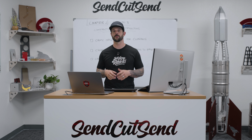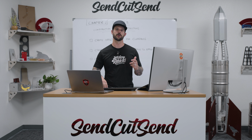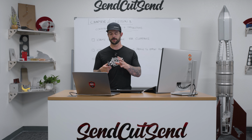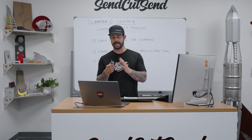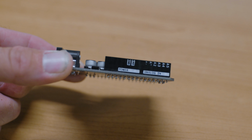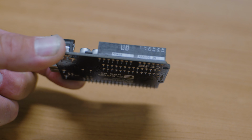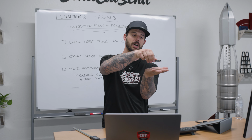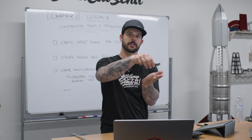In the last lesson, we successfully created an assembly that we moved our Arduino component into, and then we tied it to the origin. Now we're ready to create the bottom of our box. However, there is one last thing. I didn't model in the pins that stick through the bottom of our Arduino, and when it lays flat, the pins make contact. So what I want to do is create space, or an offset, away from the bottom of the Arduino for the bottom of the box so we have clearance.